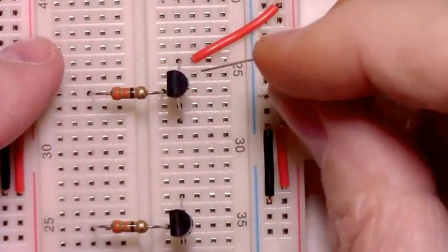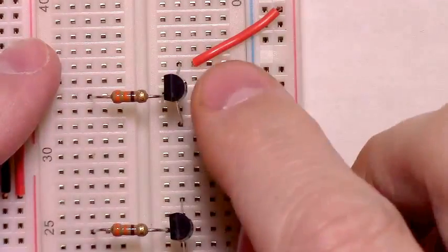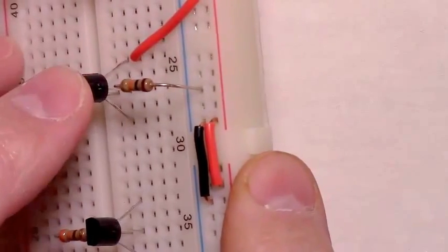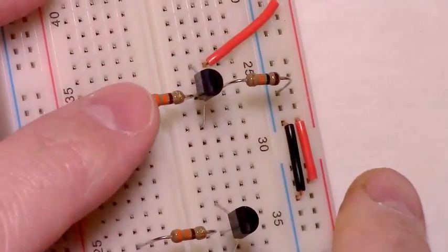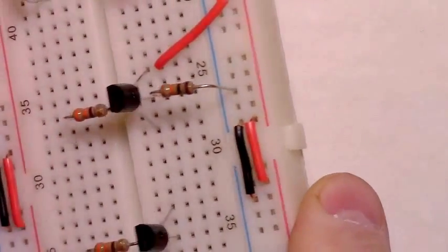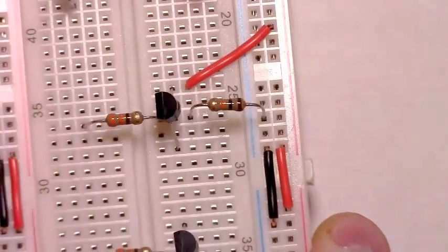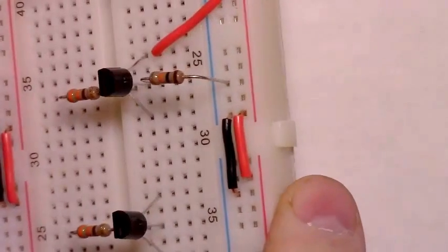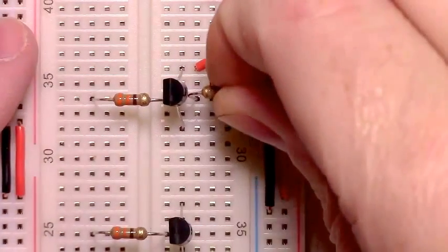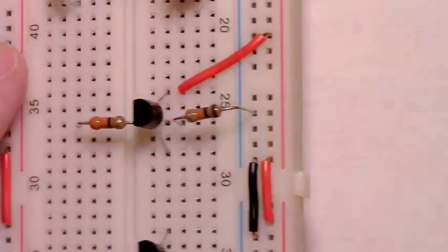It's just easier than holding perfectly true to the schematic, to go ahead and hook the 10K in the same rail as the base of the PNP, which is also the same rail that one leg of that 330 ohm resistor is connected in. It still follows the schematic functionally, but it just looks different. It's functionally identical. It's just more convenient to go ahead and jump the 10K over to ground through the base, like that.